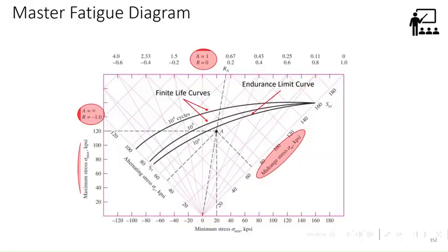How? Okay, before going into that, there is a master fatigue diagram also available. You have this mid-range, which is nothing but mean stress versus alternating stress, the stress amplitude, again plotted with your S max and S mean. Then you have both amplitude ratio and stress ratio as variables. So this is a master chart giving that.